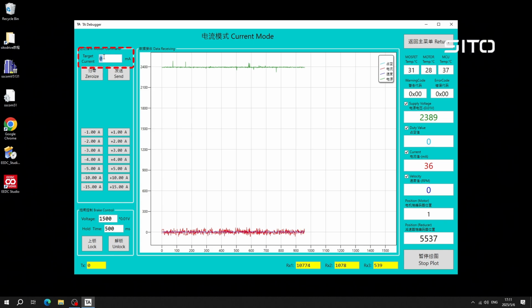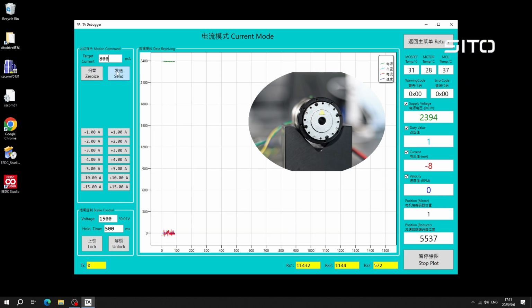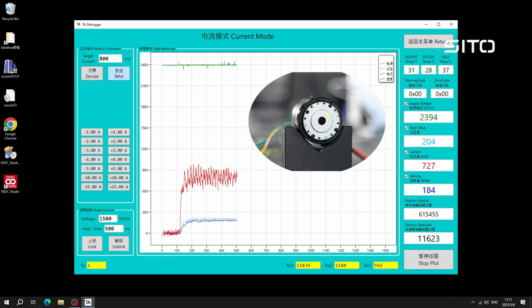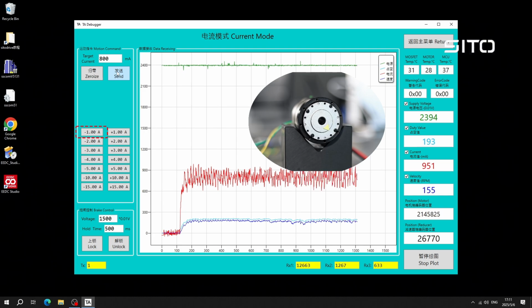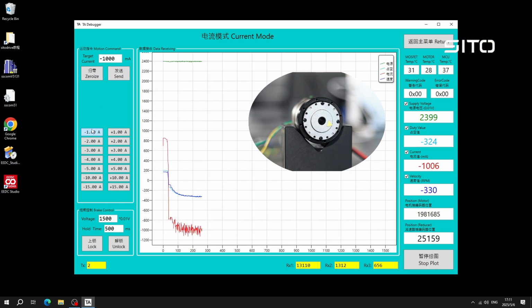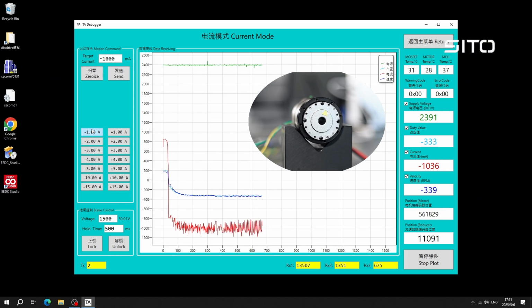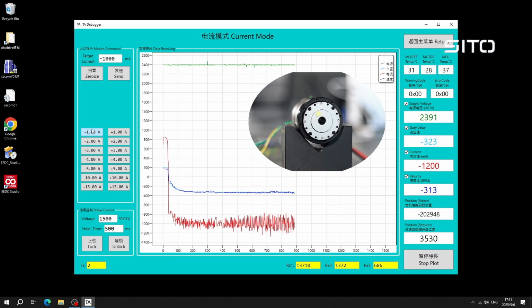Enter the current value. The actuator adjusts the current to the target value. You can also use the following buttons to send the target current directly. To change the rate of current change, you can modify the PID value of the actuator current loop once or in real time.